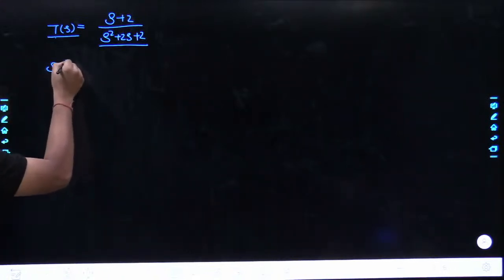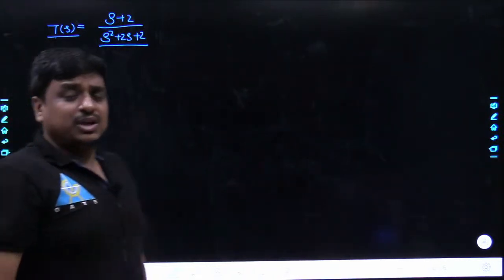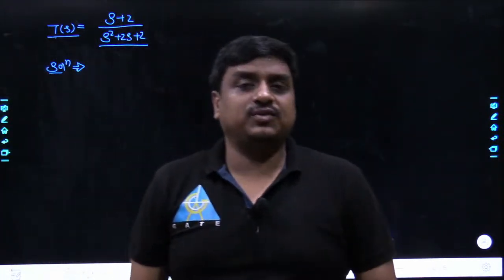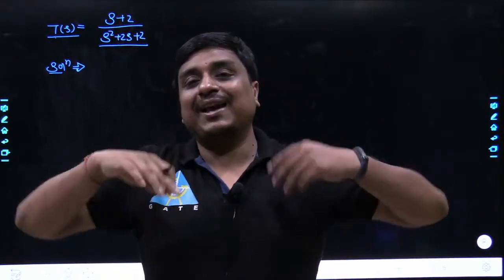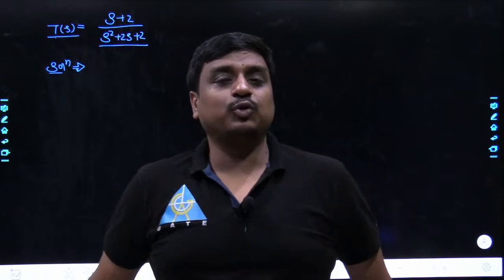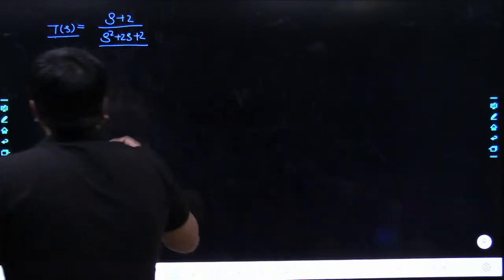You can see very well, once we focus on the poles of the given transfer function, you will get to know the poles are located at -1 plus or minus j. That means I cannot segregate the poles and I cannot do the analysis in terms of canonical form. So what would be your next approach? My next approach would be the SFG approach.